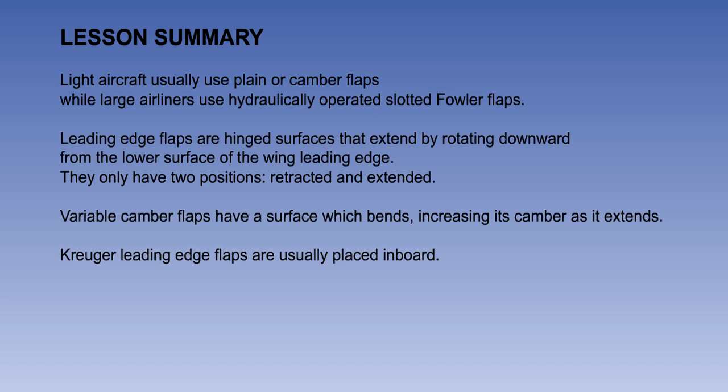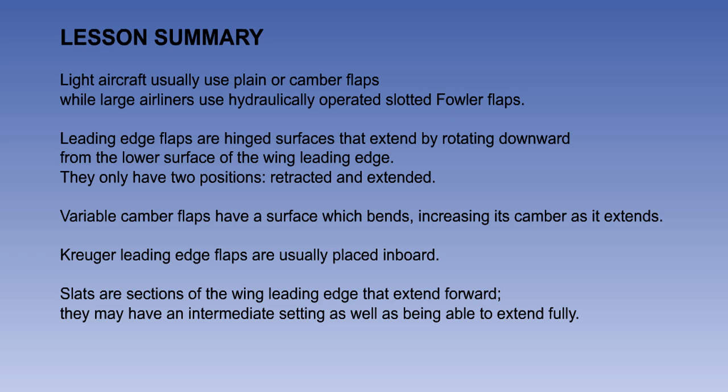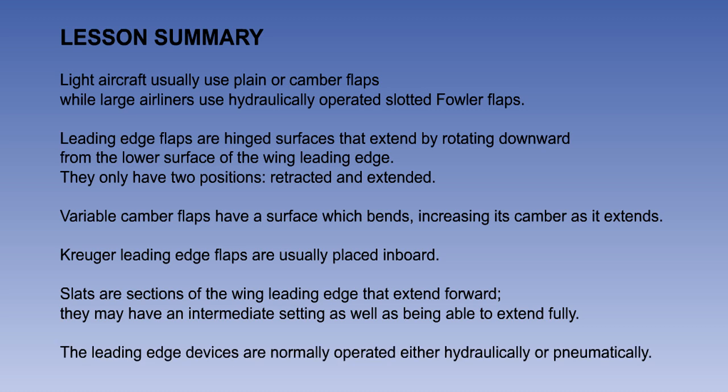Kruger leading edge flaps are usually placed inboard. Slats are sections of the wing leading edge that extend forward. They may have an intermediate setting, as well as being able to extend fully. The leading edge devices are normally operated either hydraulically or pneumatically.